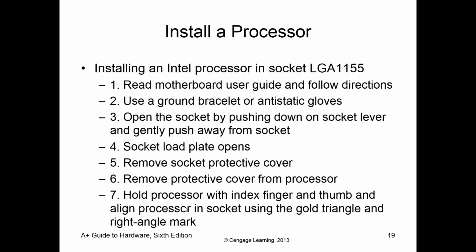Once that socket opens, there might be a load plate, there might be a plastic protective cover. We will remove that plastic protective cover. If it's not there, then don't worry about it. Sometimes it's there, sometimes it's not. But once you remove that cover, we will hold the processor from its edges above the processor slot, verifying that